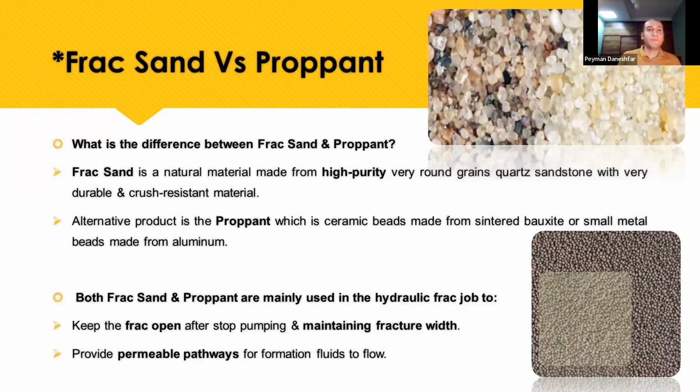But the target of both of them is to keep the fracture open and provide a permeable pathway. So we should use the same size proppant in a fracturing. It's good for us, and the opposite is not advised. What is the sentence that I want to tell you? Please don't use a lot of sizes of proppant in a fracturing job. It's not good. It is not a good result for the operations.